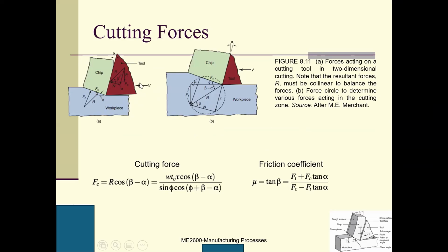If we have the cutting speed, that means your tool is going to cut this workpiece. So based on Newton's third law, the workpiece will give the reaction. One reaction is Fn, which is perpendicular to the shear plane. So we also have this Fs. Fs is the shear force along the shear plane. So as long as these two are perpendicular, they're orthogonal, that'll be okay, right?